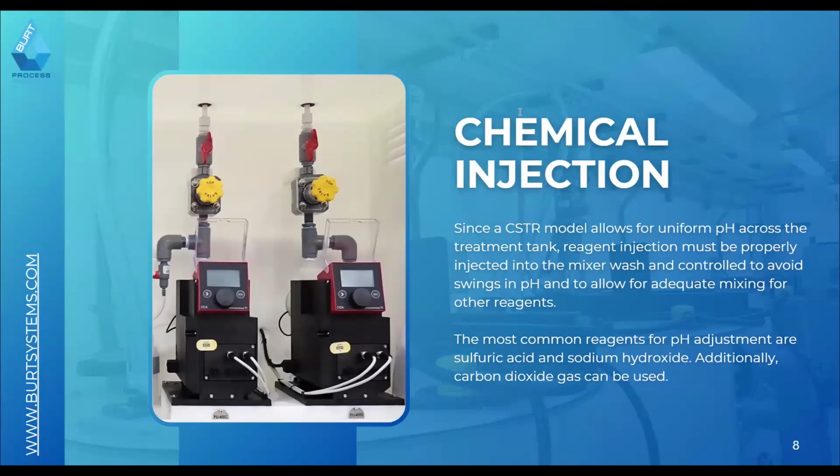When we're talking about chemical injection, this comes under a lot of different conversations. When you talk about active pH neutralization systems, which we are here, you basically are doing precision injection based on what's considered proportional control. So you're monitoring the pH as part of your system, whether that's in the recirculation line or in the actual treatment tank. And then you're essentially pulsing in to match that logarithmic curve. So whether it's 1,000 to 1 turndown or 100 to 1 turndown, which is why it's important to use precision metering pumps for these types of applications.